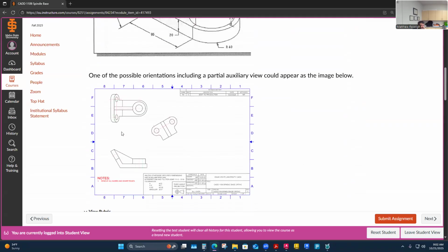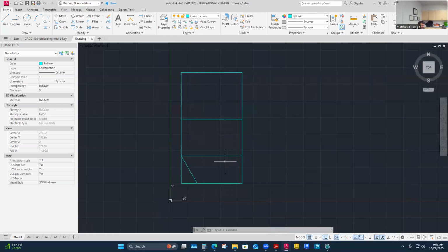I do think I ended up having to take 3 viewports of this when I placed mine in here, so I'm not going to worry too much that I have enough room to get it all in one viewport. I'm just going to continue to proceed and know that I can add more viewports. I'm going to project this out when I do it. So I do need a little bit of room. I'm going to be projecting over this way for this view. I could take the top view up higher, and I might find that I do, or I might have to project that way out further to get into a clean area to detail it, but that'll be fine. I'll be able to take my viewport from over there as well.